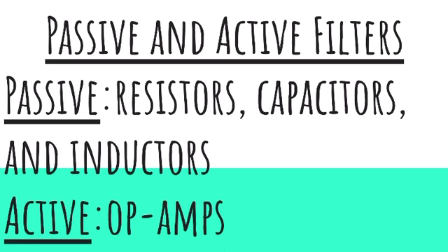Coming to the passive filters, those are most responsive to the frequency range from roughly 100 Hz to 300 megahertz. The limitation on the lower end is a result of the fact that at low frequencies, the inductance or capacitance would have been quite large. The upper frequency limit is due to the effect of parasitic capacitance and inductance.